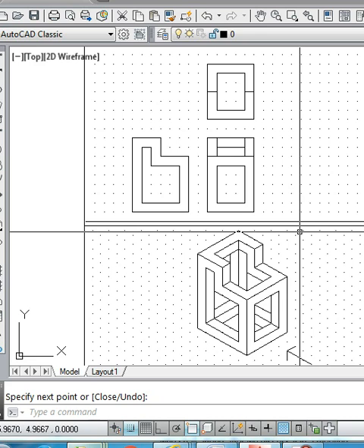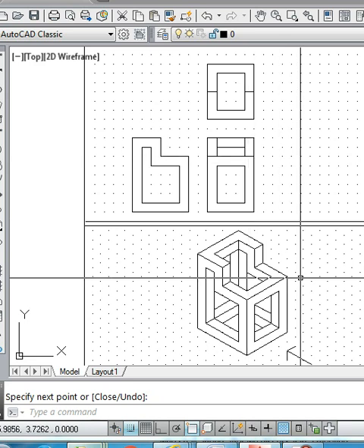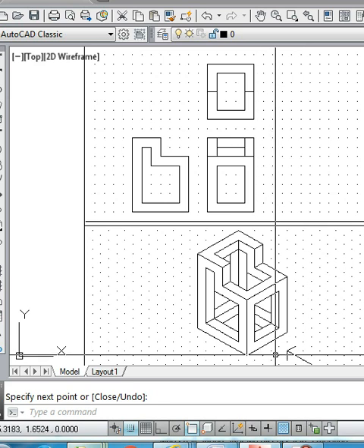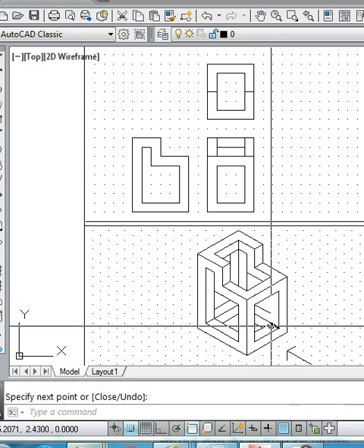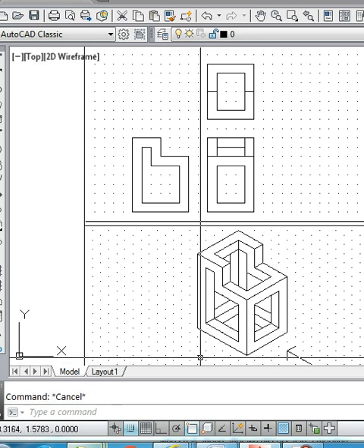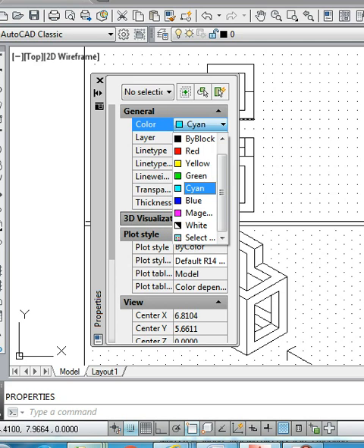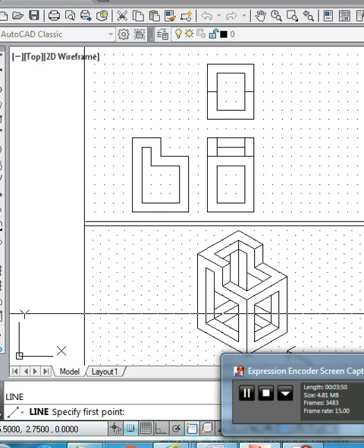So now let us focus one by one on the hidden edges. What are the hidden edges in the front view? You look from here, we can easily see there will be a line just below this one, so there will be a hidden line. Let me show the line on the isometric view itself, using a cyan color, though it is generally not to be shown.